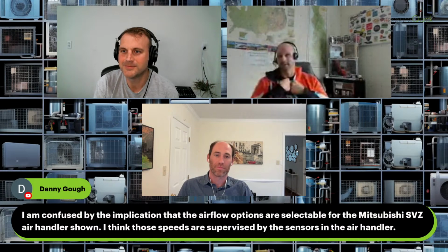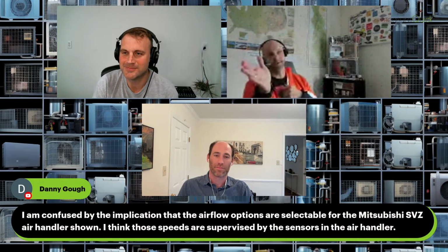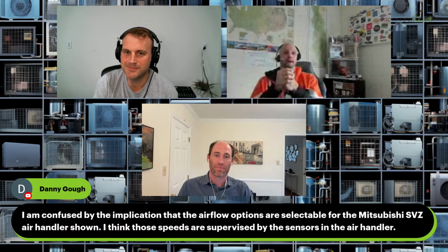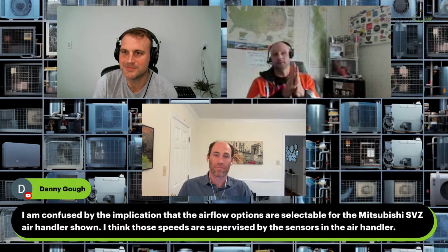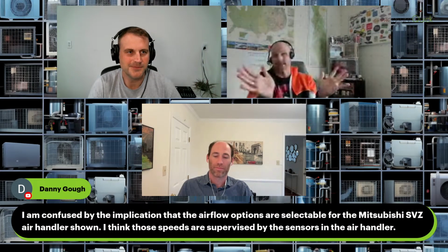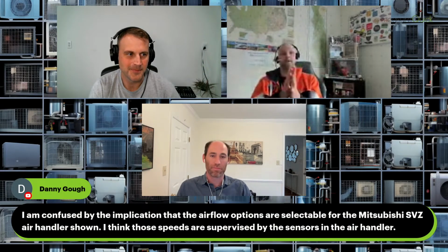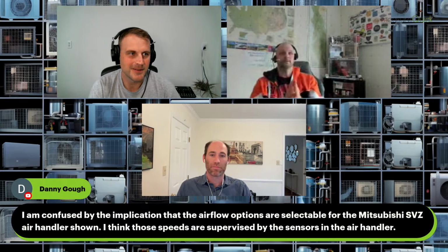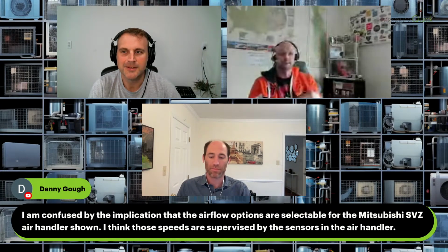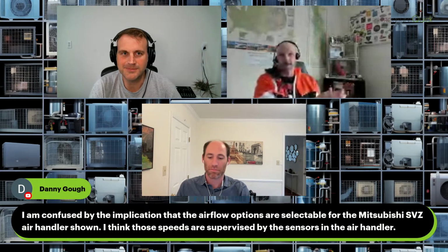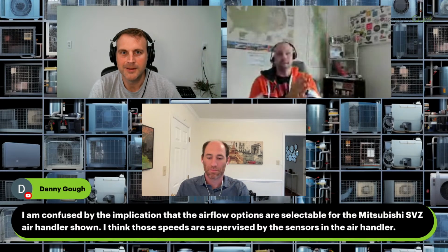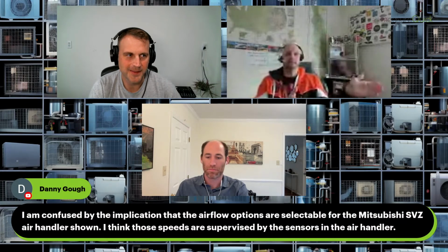I play in the Mitsubishi world quite a bit, so I have all the same pain points that you guys do. But I do know that if you take the time to use Diamond Builder, you can do a true Manual S with Mitsubishi's equipment. You can put in your design temperatures, and it will give you your latent and your sensible at design, and also other things too, like airflow or sensible heat ratio at selected airflow.